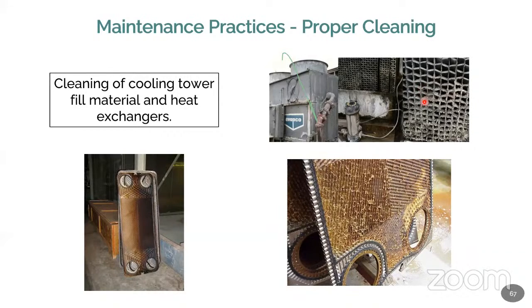Sometimes you can have a spare system. You can put in a spare, and you can clean the system and put it in the next service. So keeping a spare is a good idea, and replacing with the spare is a good idea. Heat exchangers should always be regularly cleaned, because it's a tube type, or sometimes a coil type, or sometimes a plate type heat exchanger. So each and every plate should be properly cleaned, and check that the inlet and outlet fluids have proper heat transfer capacity taking place.